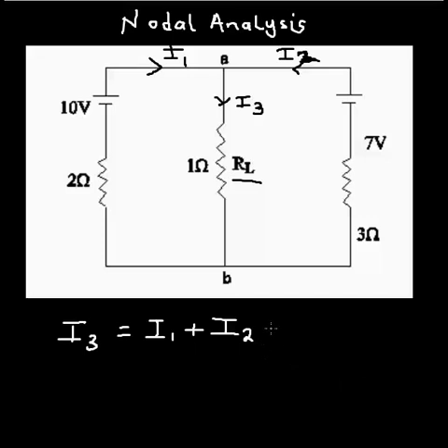I just have one unknown here, just one node, so that one node is going to be one unknown. That is why my KCL is just one equation. So it's a very simple nodal analysis. The node I'm considering has voltage VA, with respect to the negative connection, with respect to ground. So this is my ground.